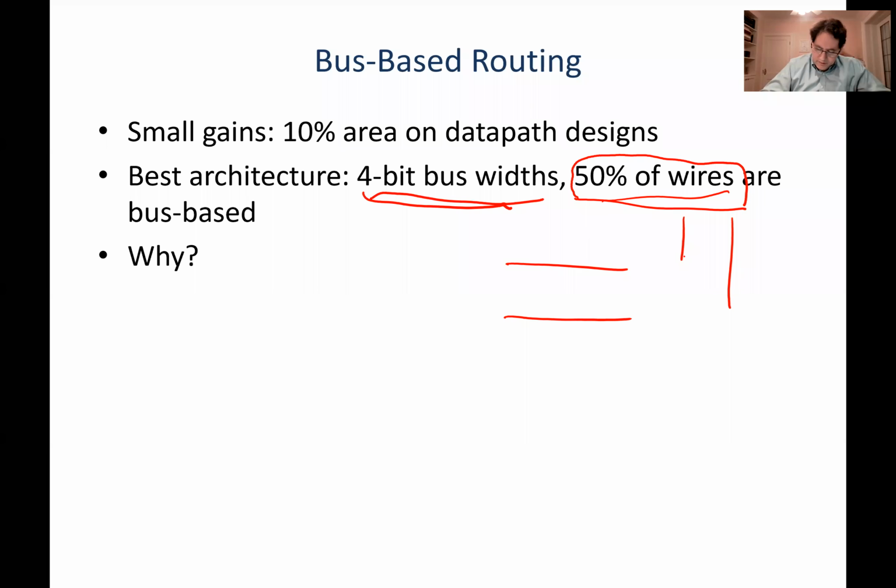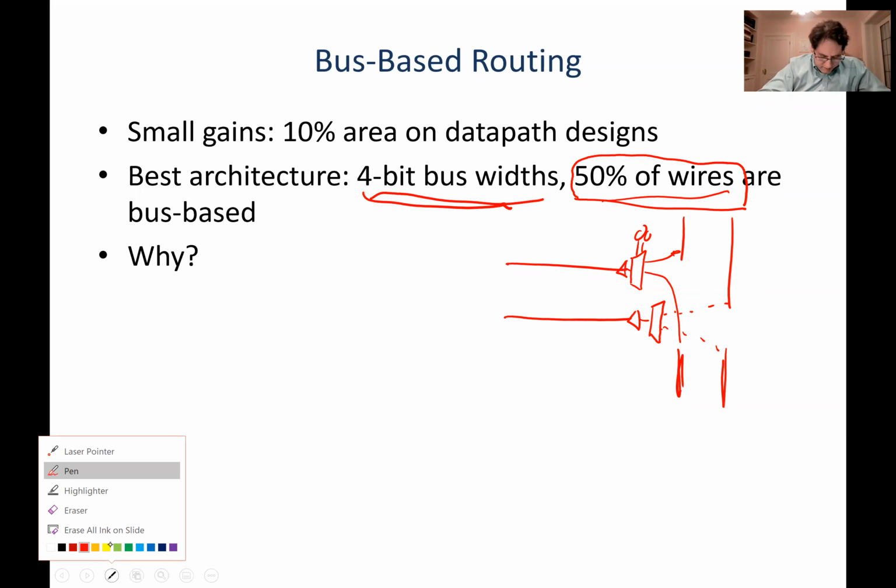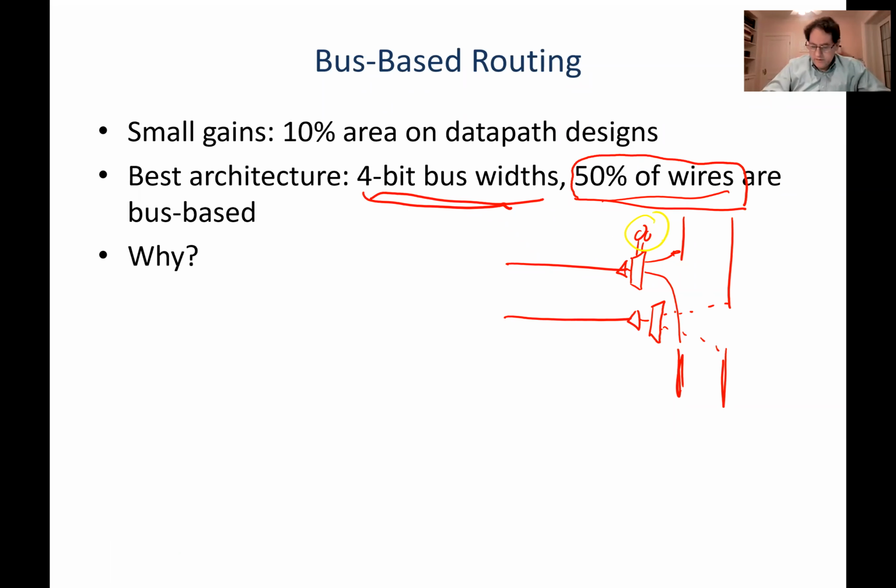So what they're actually doing is, normally you would build a routing MUX that drives this wire, and you would have configuration cells that control which input is going to go into it. So maybe it takes its input from there, maybe it takes its input from down there or somewhere else. And what they're doing is basically saying, okay, well, let's think about buses where this guy also could take a signal from the wire that's above or the wire that's below. And the only thing that they're actually saving, they're not getting rid of the muxes. What they're getting rid of are these CRAM cells.